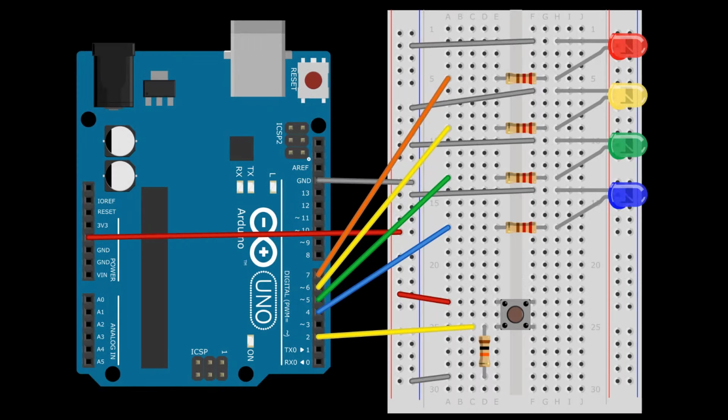Although we didn't see it here, it's common for the Arduino to incorrectly read multiple button presses from a single button press. To correct this, there are methods called debouncing, which ignore accidental duplicate button press reads. While we could code this ourselves, it's much simpler to use an existing library to debounce.